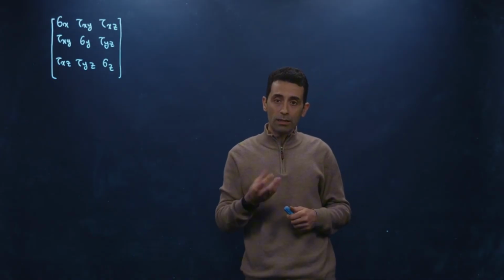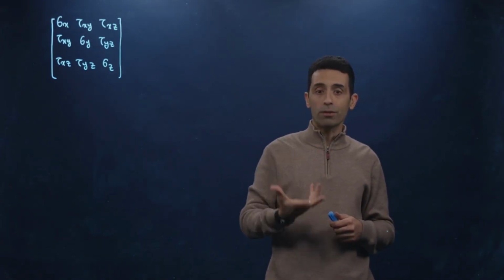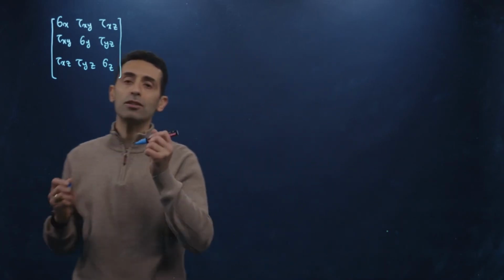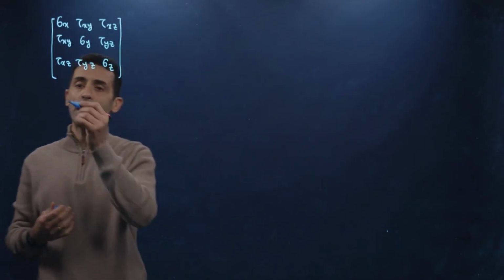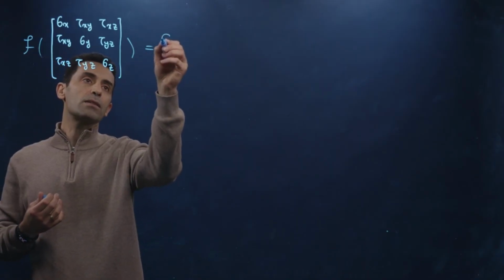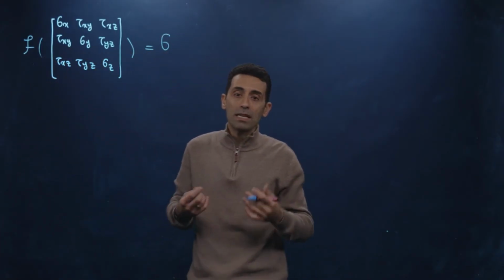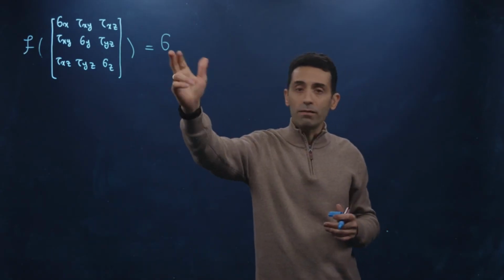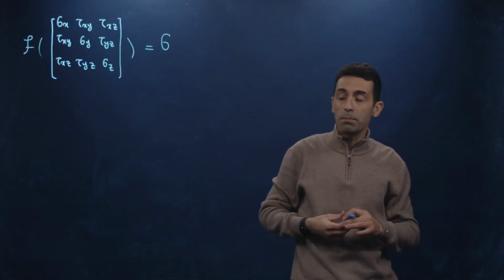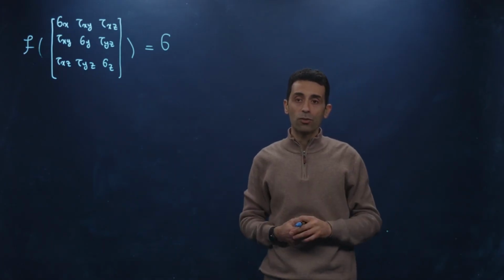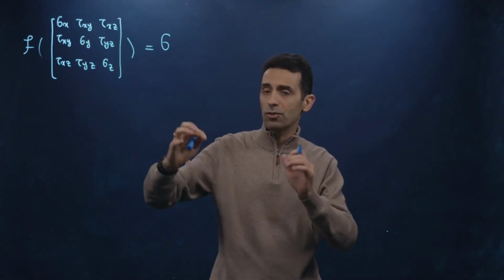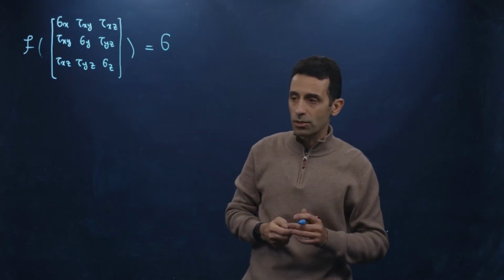It can obviously get really complicated, but don't worry. We have already learned about failure criteria, so we can use our criteria to come up with an equivalent stress out of these 6 components. So essentially we put this into our failure criteria. So let's call it function f, and that gives us something that we call sigma. So this is our equivalent stress. This can be the von Mises stress, this can be the maximum principal stress, this can be the stress intensity. It depends on the material that you are looking at. Okay, so far this has combined the stress tensor to give us one equivalent stress.